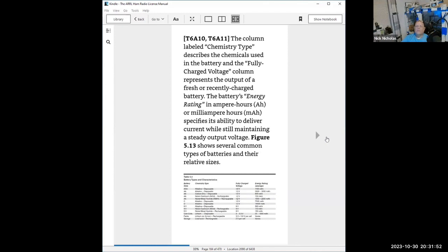So lithium batteries have a protection circuit called a battery management system added in. Never run a lithium battery without one. Don't hack lithium batteries. Lithium batteries generally, except real tiny button ones, have battery protection or battery management systems. There's a circuit board that monitors the battery during charge and discharge, cuts off the charge when it gets to a certain point, and cuts off the discharge when it gets to a certain point.